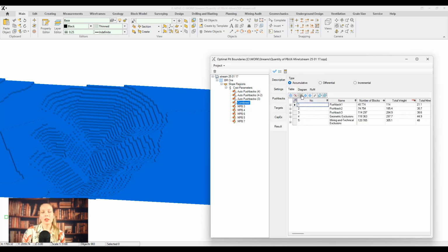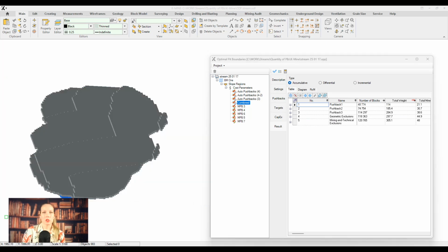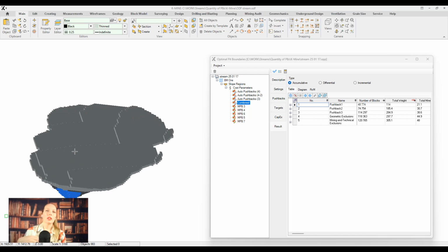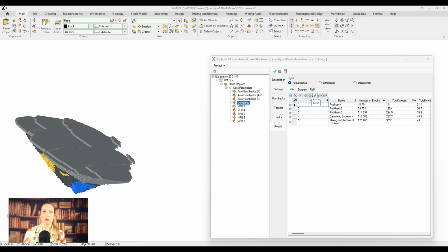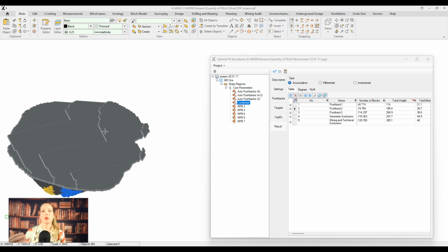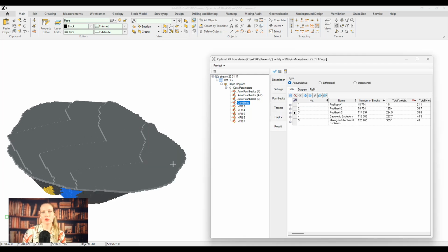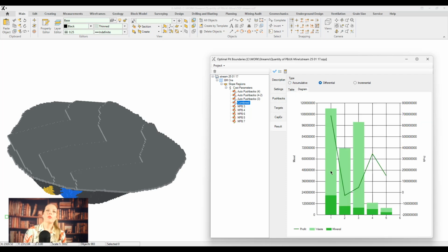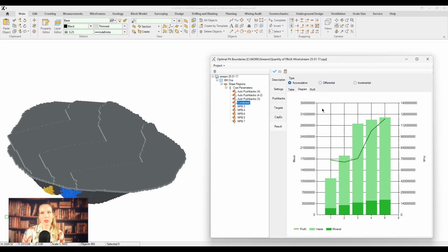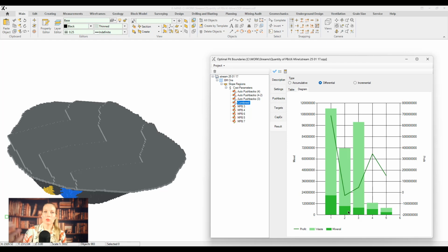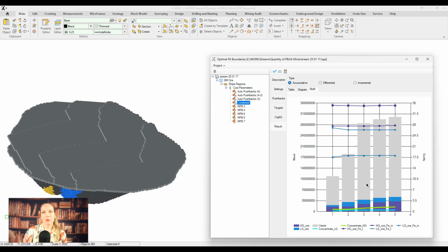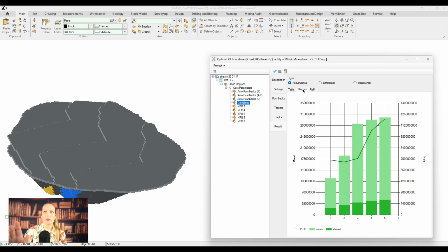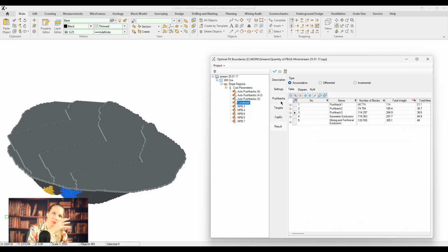For example, within the pushback restrictions, you might specify one of the wireframes that show the optimization calculation result. Then you set the target parameters for finding all subsequent pushbacks, and the calculation kicks off once you start building the second pushback, with the first one being set according to your restrictions. So you see that out of 3 pushbacks, 2 were automatically generated and 1 was manually set using a wireframe. And this approach is great if you know exactly how you want to begin, but there are still things to figure out for the next steps.